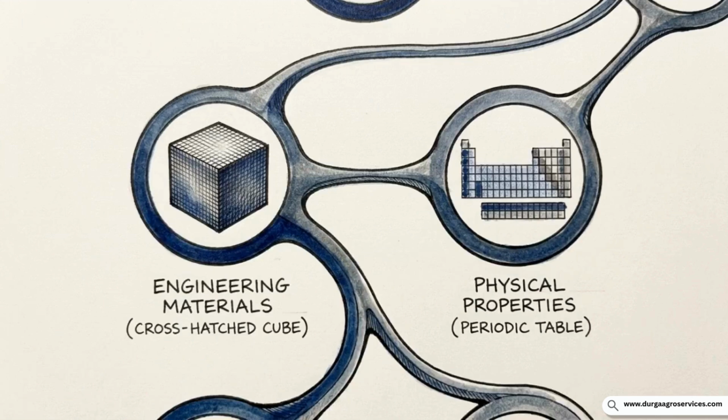This flowchart breaks down the universal pipeline required to run a simulation. To get accurate predictive data, an engineer must transition a raw 3D model into a strict mathematical environment through 5 steps. We start with the base geometry. Next is the material phase. The software needs to know exactly what it is testing. The engineer inputs specific values for density, yield strength, and thermal conductivity, so the system understands how the physical matter will behave.